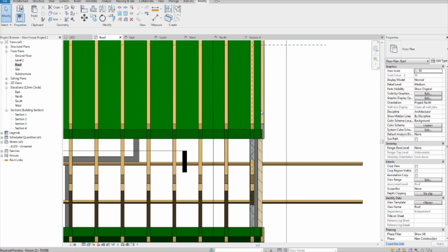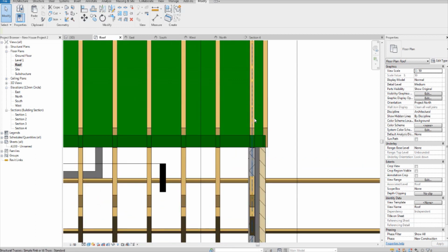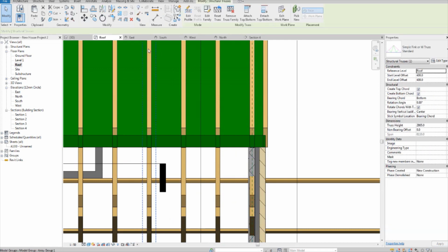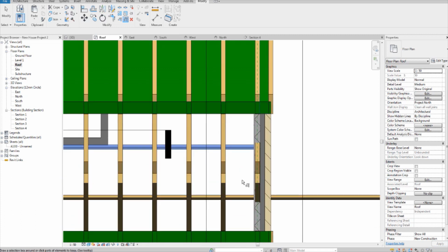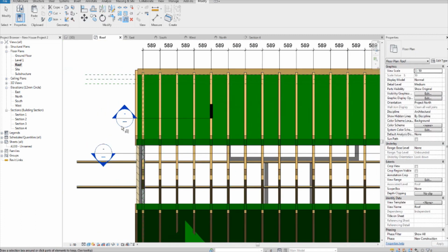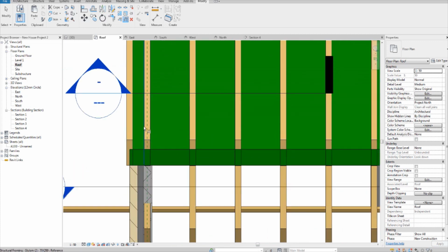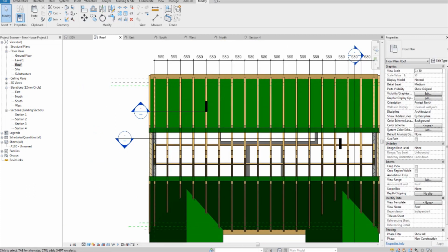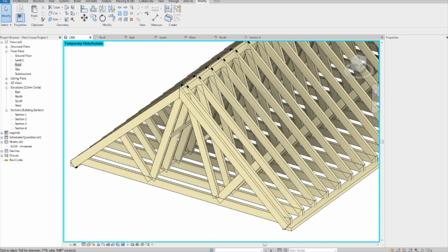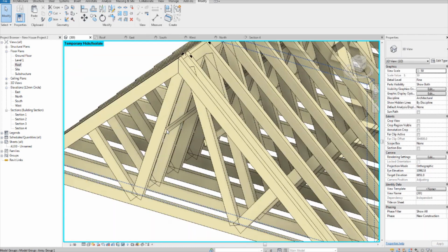And I want my purlins to go to the end of this, the last truss on the structure here. So use the multiple trim and extend tool and select this, the very edge of the truss on the plan view, and trim them down. Simple, easy. And do the same for this side. Trim them down. And in 3D, look at that. So beautiful, isn't it? Perfection.